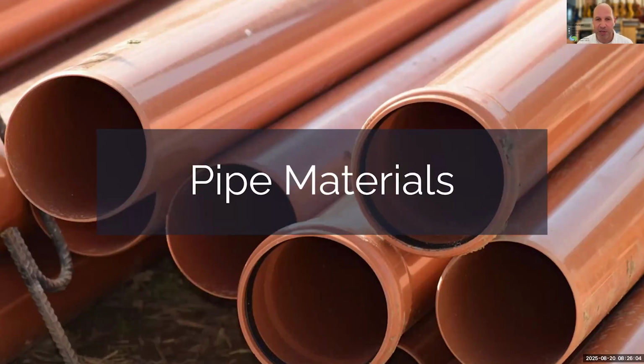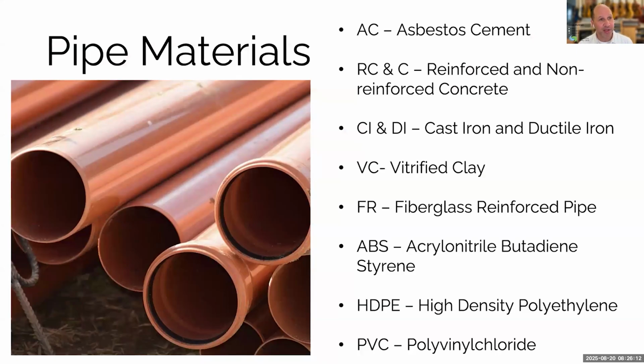There are four categories of pipe that you're going to run into: metallic, concrete, clay, and plastic. Broken down, you've got asbestos cement and reinforced and non-reinforced concrete in the cement category. For the metallic category, you've got cast iron and ductile iron, which aren't used very much except in very specialized applications. Then you've got vitrified clay, which is a category of its own. And then you've got fiberglass reinforced, ABS, HDPE, and polyvinyl chloride options, all of which are different kinds of plastic that have different benefits and